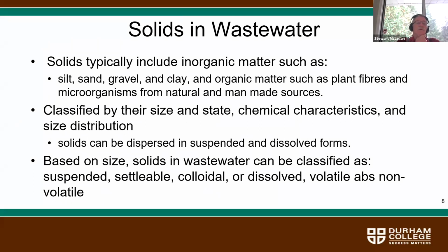Great. Solids in wastewater. Solids typically include inorganic matter such as silt, sand, gravel, and clay, and organic matter such as plant fibers and microorganisms from natural and man-made sources. They're generally classified by their size and their state, their chemical characteristics, and size distribution. Solids can be dispersed in suspended and dissolved forms. So that's a key point to take note of, is that these solids can be present as suspended solids or as dissolved solids.